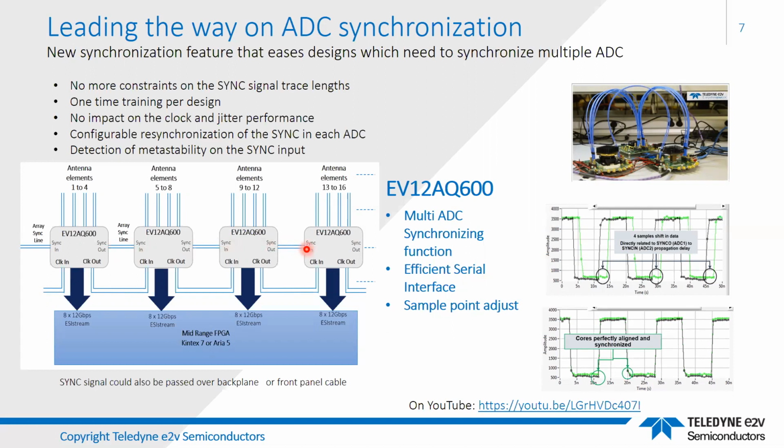Up to now, synchronization signals have needed to be fanned out using a fan-out buffer that requires another component on the board, and so increases your requirement for board area, increases the power supply requirements, and it also needed the design of this to be done very, very carefully, because the routing of this and the skew calculations that were needed were quite exacting, and they added another level of complexity to a board design.